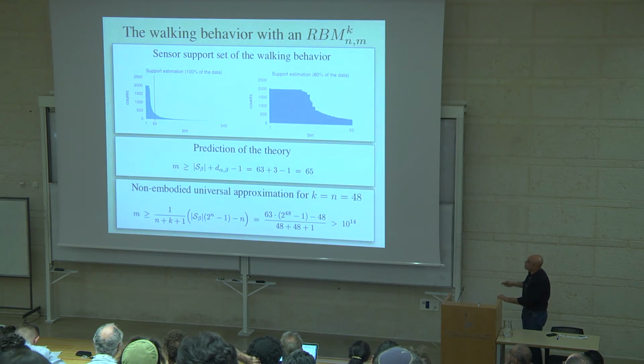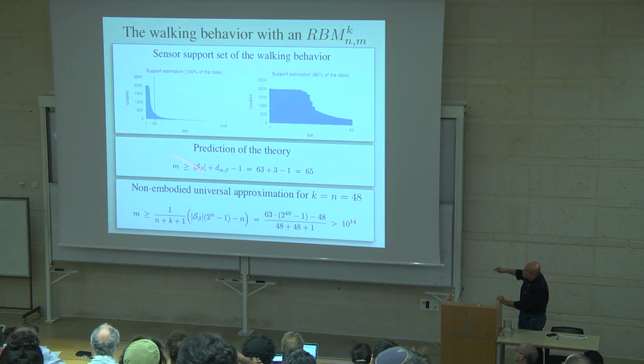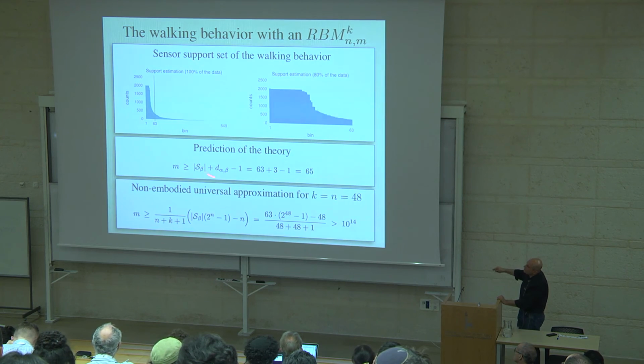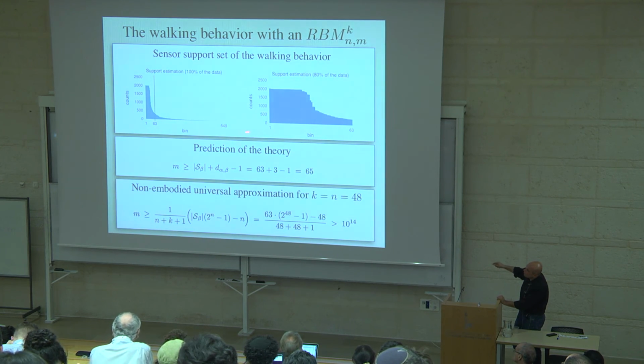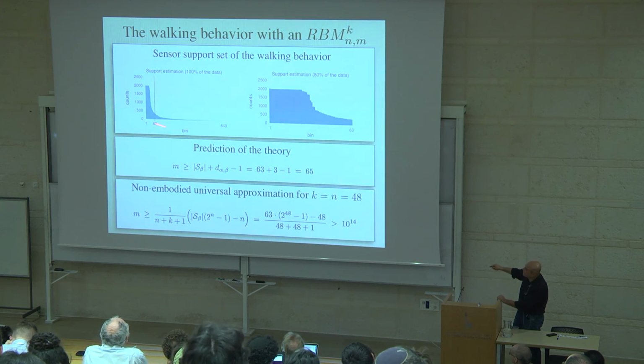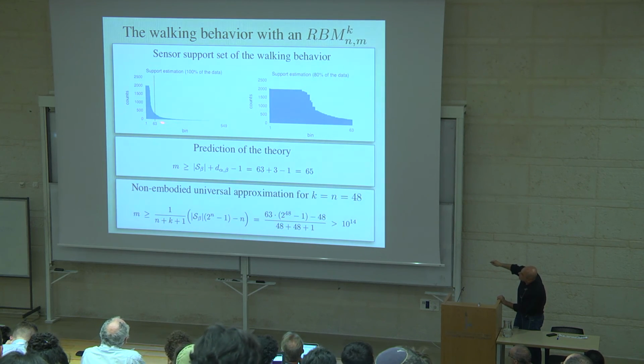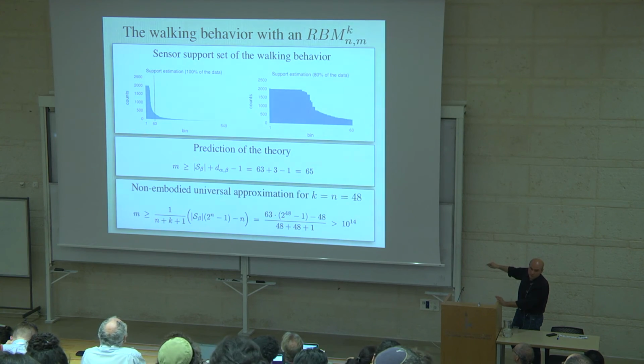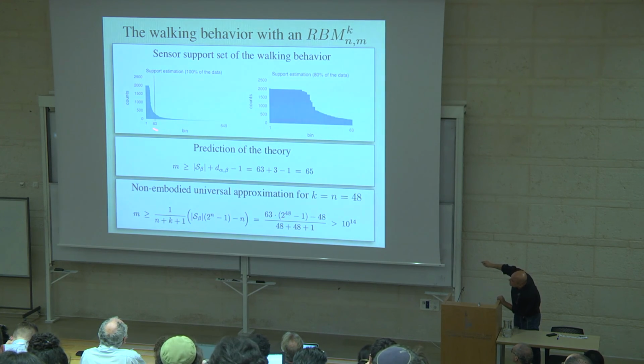So in order to do so, we count the number of sensor states. If you remember this S beta, it's the number of possible sensor states. Here's a histogram of all sensor states, and here's the wishy-washy part of this strategy. We simply take, I think, 80% of the possible sensor states. We have no reason for that. And this gives us 63 sensor values.